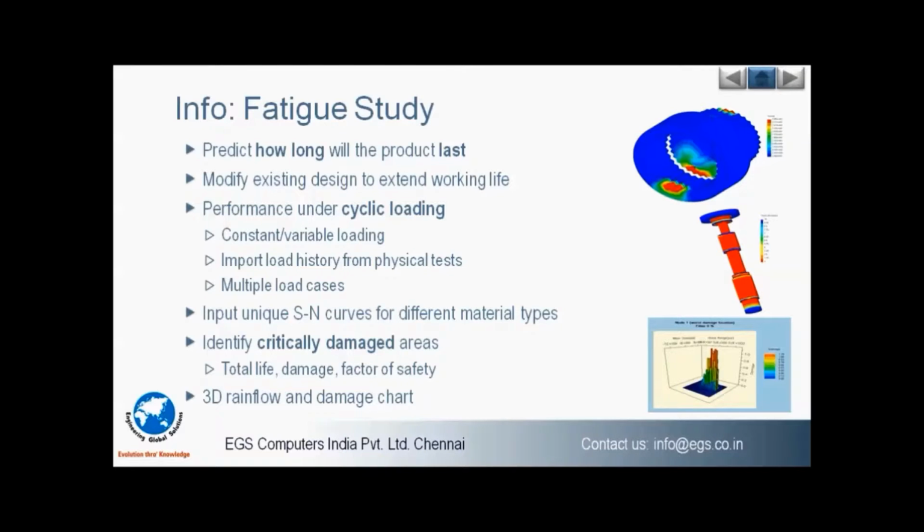And we can import all this history using the physical tests of your products. The material library is one such good thing inside SolidWorks simulation, as the user can directly access the SN curves which are inbuilt inside the material database. So using this, we can calculate the total life of a product, damage, and the factor of safety.